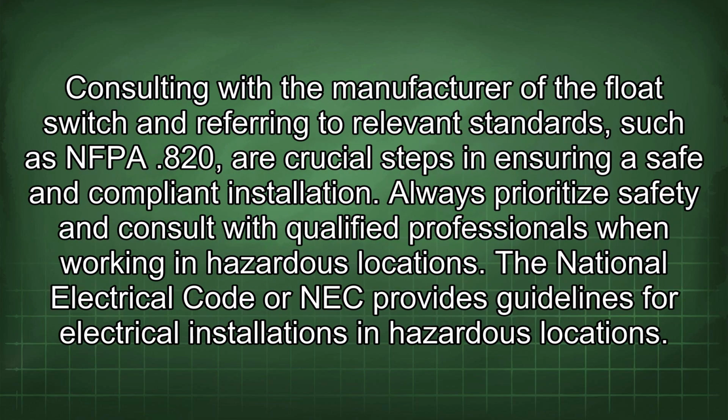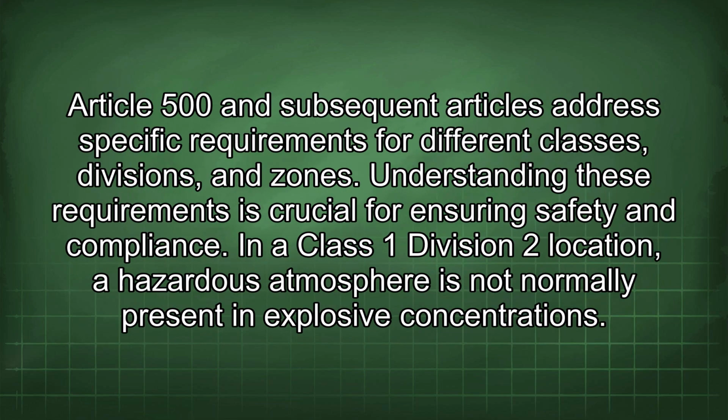Consulting with the manufacturer of the float switch and referring to relevant standards, such as NFPA 820, are crucial steps in ensuring a safe and compliant installation. Always prioritize safety and consult with qualified professionals when working in hazardous locations. The National Electrical Code, or NEC, provides guidelines for electrical installations in hazardous locations. Article 500 and subsequent articles address specific requirements for different classes, divisions, and zones. Understanding these requirements is crucial for ensuring safety and compliance.